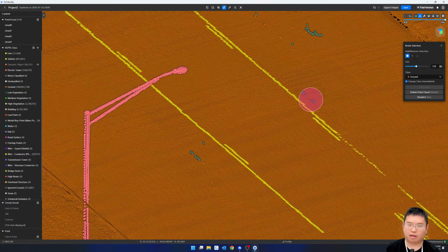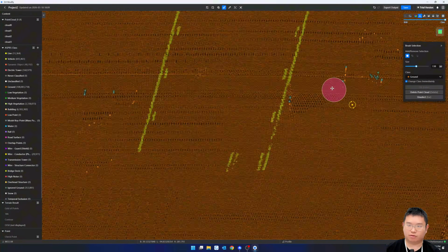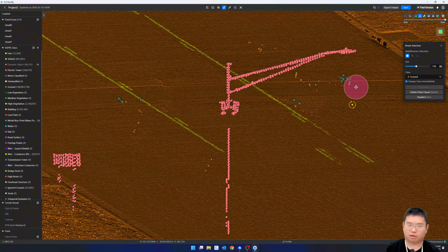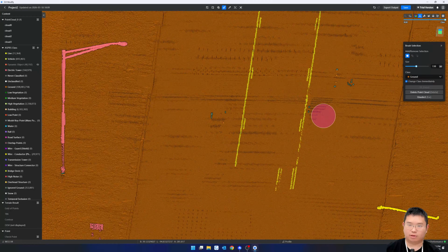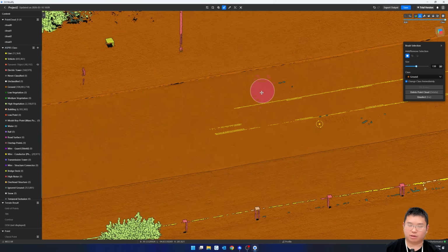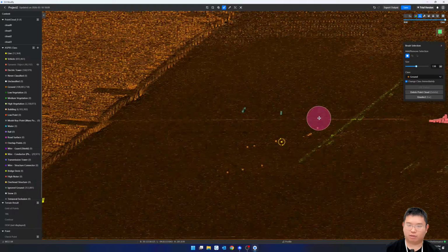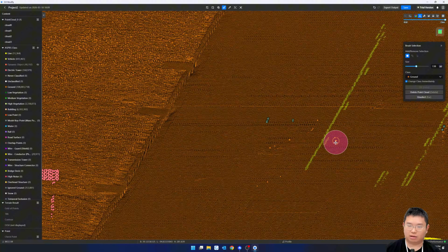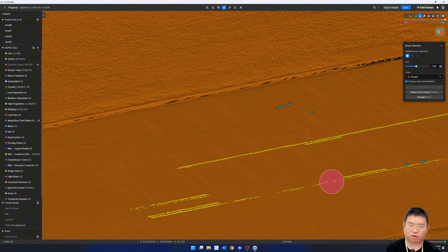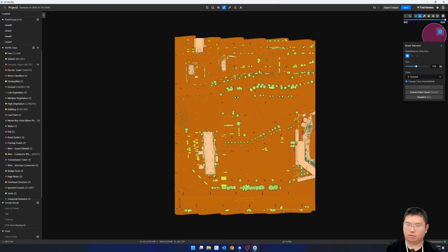Okay, and what about these noise points above the ground? They're extremely close to the surface. How am I going to solve or classify these out, right? That's a unique scenario. If I experience something like this, I like to remove noise points away from my surface. Something I would do is use a vertical profile to enhance the visibility of these noise points and separate them from the surface. By doing that, I'm going to change my perspective to top view, of course, ortho.